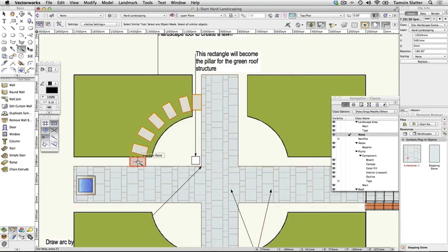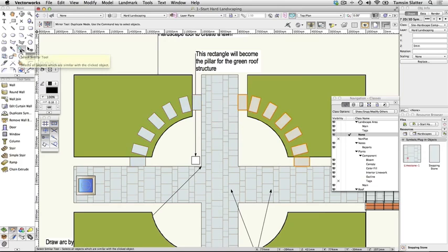From the Basic palette, choose the Mirror tool. Draw a vertical reflection line as you did earlier to mirror the lawn, using the top midpoint Q of the central vertical path to find the centre of the design. Notice the preview of the mirror operation that is displayed before the second click. Click Select Similar again with the same settings and select all of the symbols. Use the Mirror tool again to reflect these through a horizontal reflection line, using the midpoint Q on the horizontal path to find the centre of the design.